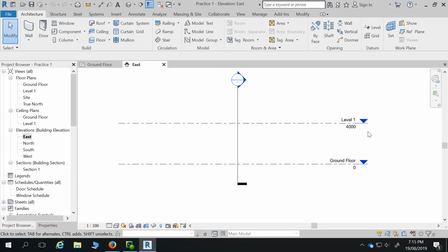Now, what we tend to do is, if we had a template at work or something, we would probably already have our levels for a single story, what we would use. If it's 2.4 ceiling or 2.7, we'd have that set up. But what we need to do in this case is to actually set up some ceiling height. So this next exercise that we're going to do actually comes from the Learn site. Oh, not that one.